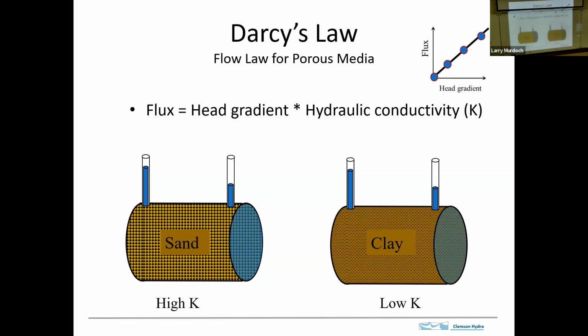And so yeah, it became law. It's Darcy's law, and under laminar conditions, the flow rate is proportional to the head gradient. So it says the flux is equal to the head gradient times this factor called the hydraulic conductivity. So if we were to make a plot like that, flux as a function of head gradient, the hydraulic conductivity would be the slope of that line.